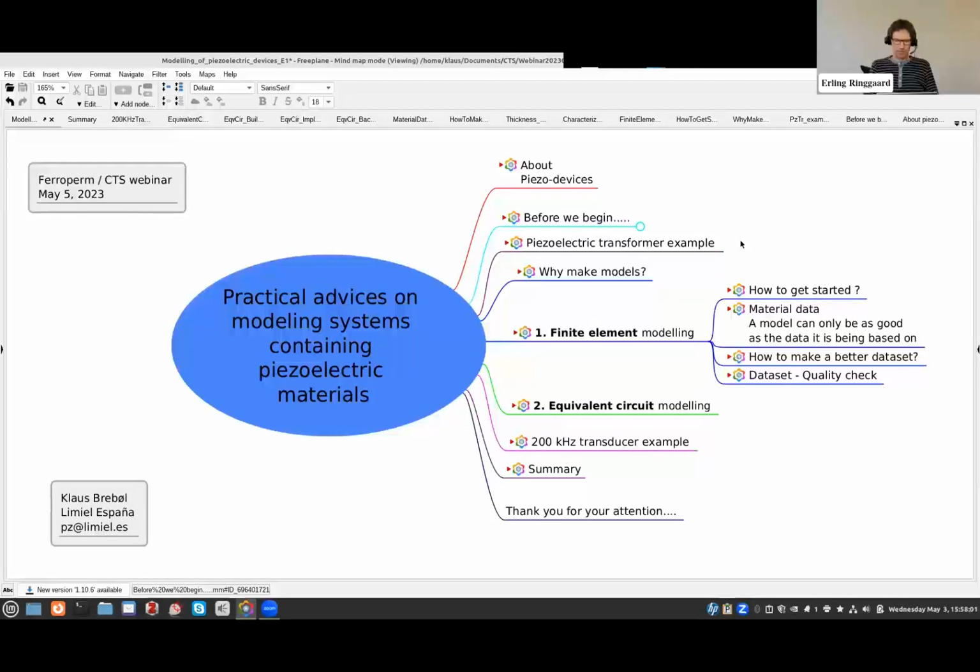Yeah. But I guess that fatigue is a difficult problem. I guess you can also see a certain spread in parameters there. I mean, I have a certain experience with fatigue in metals for high power transducers. And for instance, if you buy the same titanium alloy from the same supplier, but it has been machined in different ways, you will see different fatigue behavior. So I think it's quite a can of worms that you are opening if you begin to do this. So yeah. Good luck.